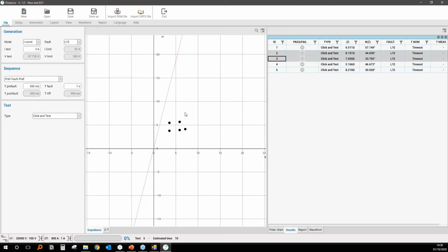So different trip times will indicate that the border is between two zones. Trying to explain in a simple way, the algorithm will do several tests in order to look for different trip times. Once they find magnitude and angle of impedances where this threshold has been found, then there is indication in the table that that value is a border between two zones.